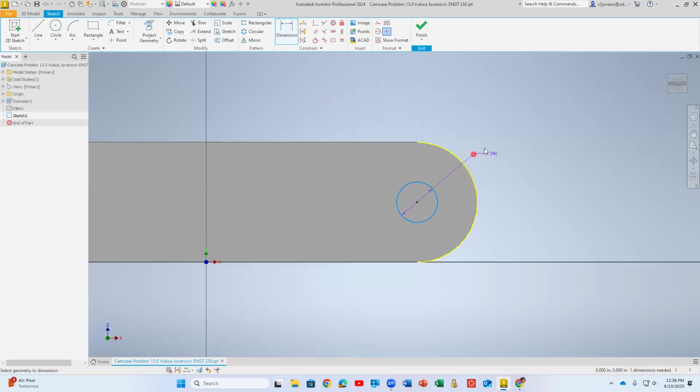And then dimension this circle by 0.25. Then click escape, and we can convert this to something we're not using, by selecting the yellow and selecting this. Because anytime you put two things together in a constraint, that means you're using the other one for information. That's why it became like that.